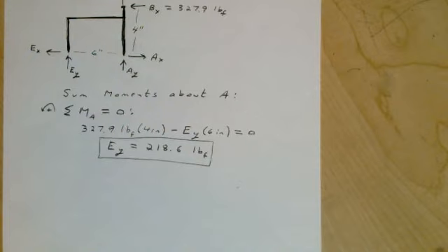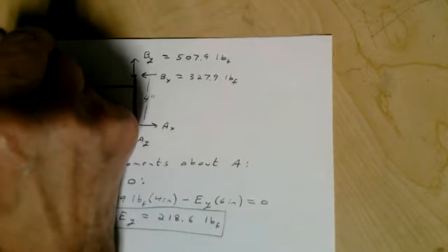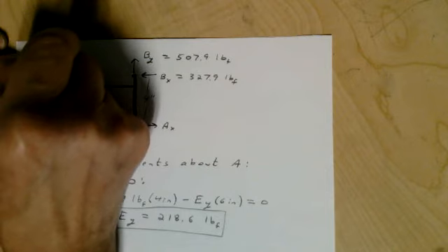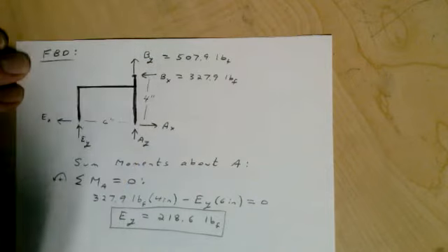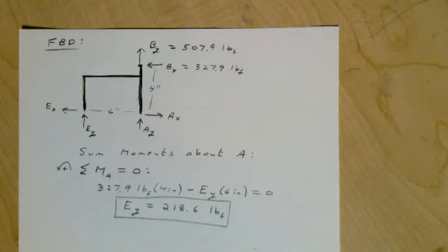So once again, on these machines, take it apart, go from part to part, and carry your forces along. And again, it's really critical to make the free body diagram. So here we have the free body diagram at the end here, and that solves the problem.